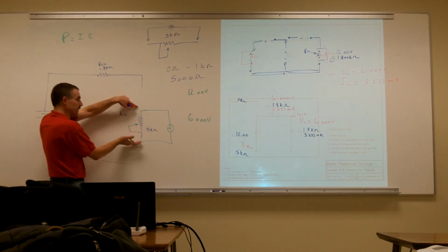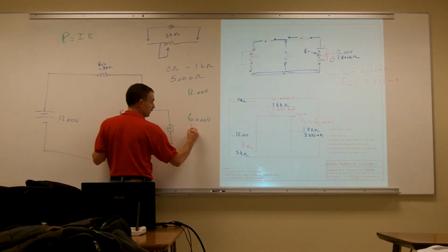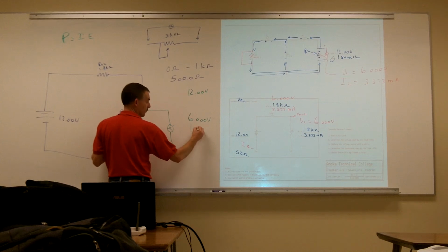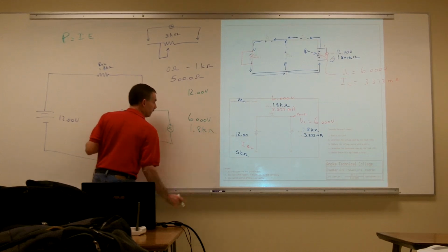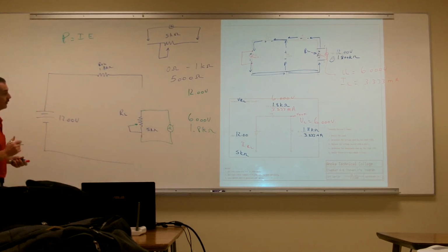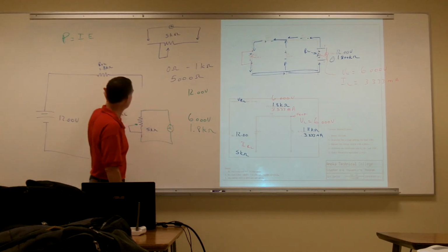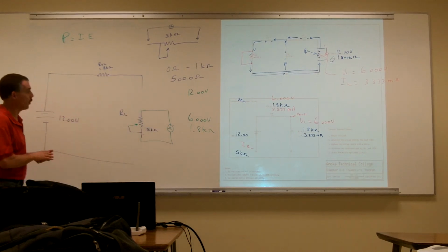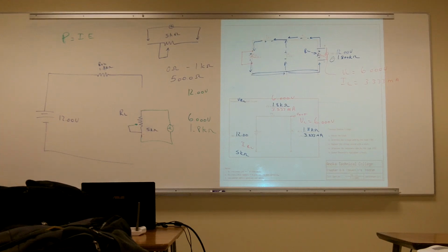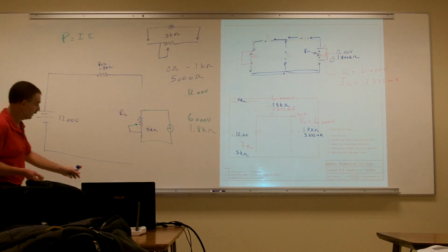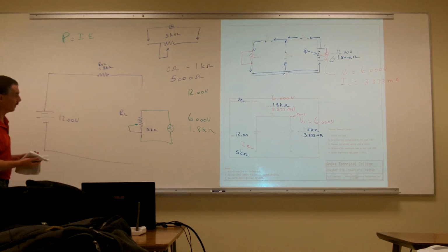And when I measure that resistance, it's probably going to equal what? 1.8K. 1.8 kilo ohms. I know that it's going to match the internal resistance of my device. And at that point, I know that my impedance is matched to the impedance of my source. Anything at 1.8 kilo ohms is going to have my maximum amount of power. That's when I'm going to be able to emit the most power across my load.